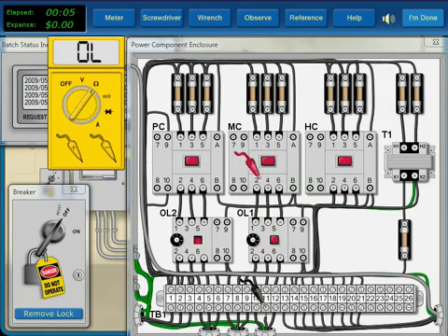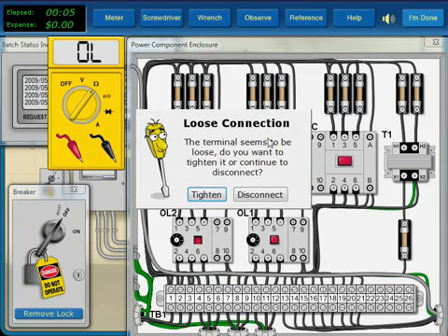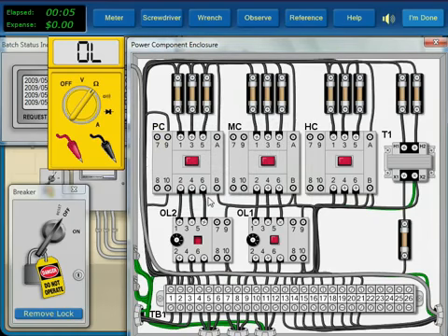We split this area in two at the bottom of the contactor. The low resistance reading tells us the open is above the test point. Testing at the top of the contactor with it closed indicates the contact is okay. Now, the only possible causes are one wire and its connections. We begin to disconnect the wire, but find a loose terminal. Since this fits the symptoms, we tighten the terminal to repair the circuit.